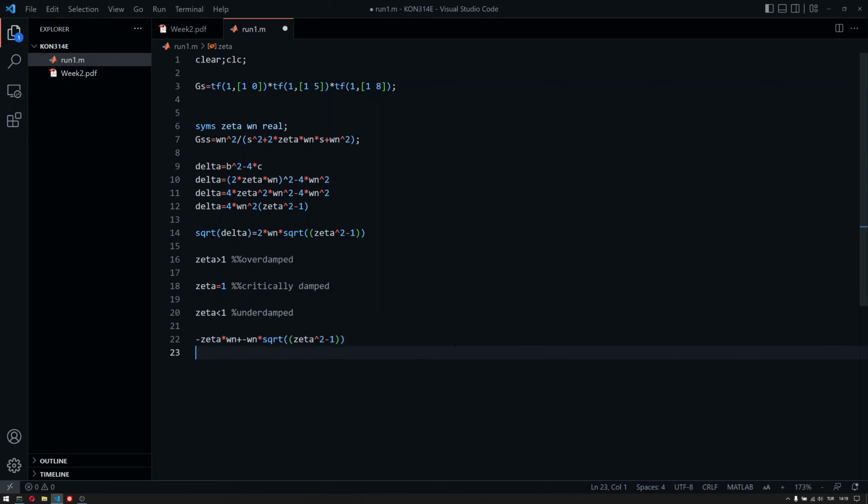There's also this nice thing that we know the settling time of underdamped second order transfer functions. Now the overdamped and critically damped transfer functions are most of the time not even considered because we don't really know the settling time of them. But we are interested in underdamped solutions because most of the time we will have overshoot. These don't have overshoot, so that's that. We know that the settling time of such systems is approximately, again, 4 divided by zeta times omega n.